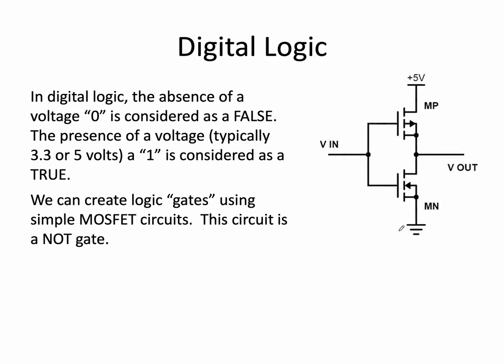And you're like, whoa, what's going on here? A NOT gate: if you put in a positive, you get out a negative. Well, this is an N-type one down here, so that positive input turns this on. This symbol here stands for ground, or 0 volts. It connects the output to 0 volts, so you get 0 volts out here at the output. You get 0 out if you put in 3.3 volts over here. This is a P-type up here. The positive does not turn it on.